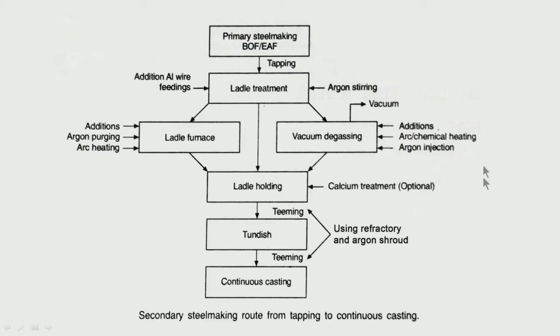If you take all these cares, all these measures and do all the controls, it can be further controlled to even less than 15 ppm. So, for getting a good quality of steel, we have to be very careful at every stage, starting from cutting out the primary slag using a slag stopper, and then taking whatever precautions or steps are necessary at every stage of secondary refining: proper deoxidation, proper argon stirring, proper heating if necessary, because in the process we have to pass through so many steps.